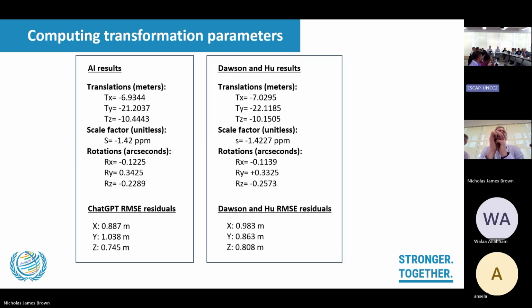We will make sure that that goes into the EPSG. So we found issues when we were using surveying software and the GIS software where the transformation parameters were different from what we had established back in 2008.